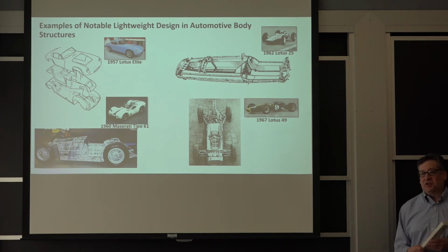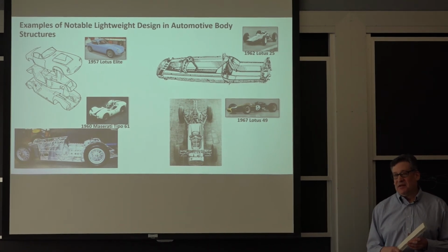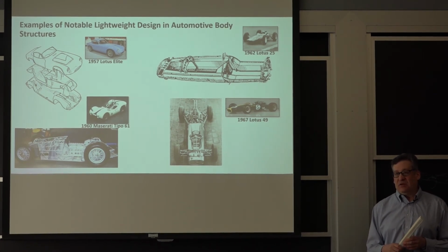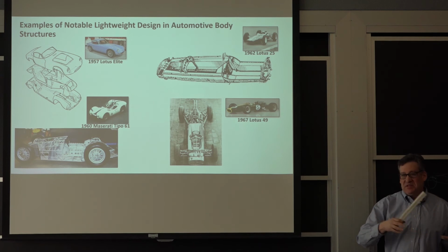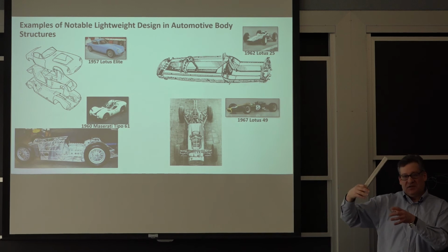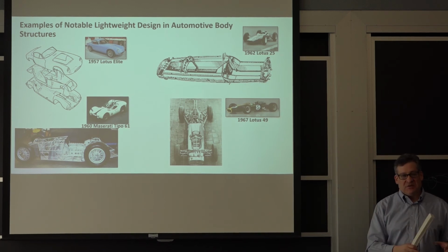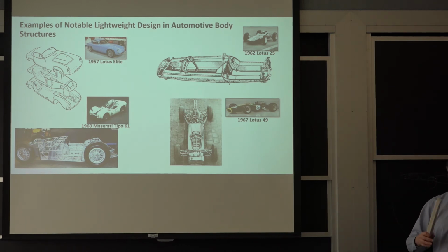What the electric car companies have done is they have used the battery housing as a structural member. BMW has a scooter that they sell in Europe where the front of the battery housing has some mounting points, and the back has some mounting points. The steering system, the forks and everything, mount directly to the battery box, and the rear suspension mounts directly to the battery box on the backside. So the whole bending load taken up by the scooter is taken up by this battery box.